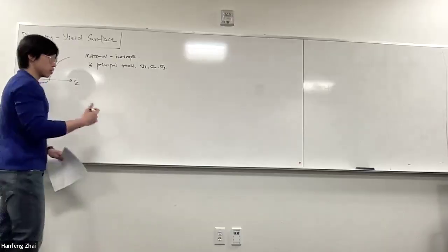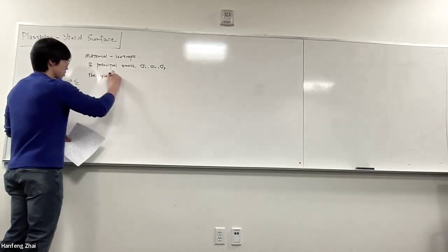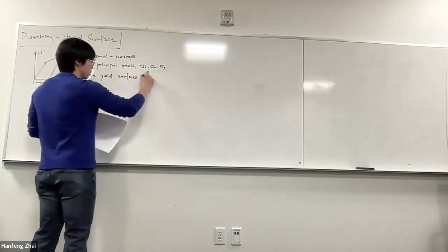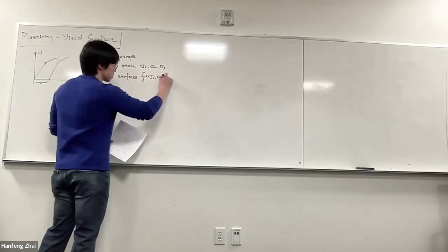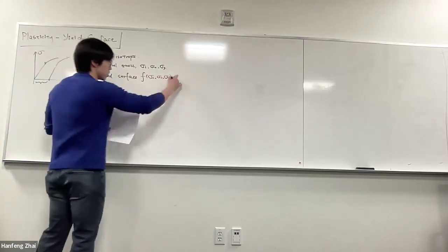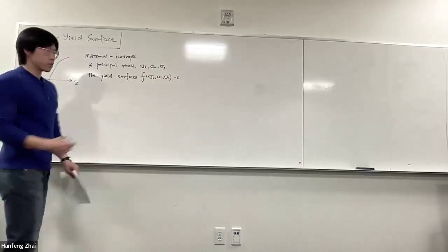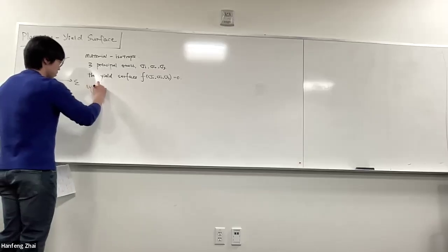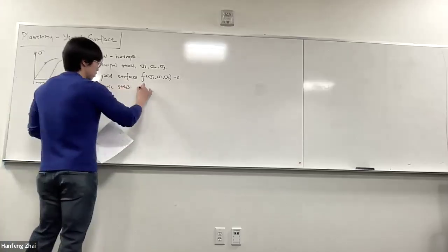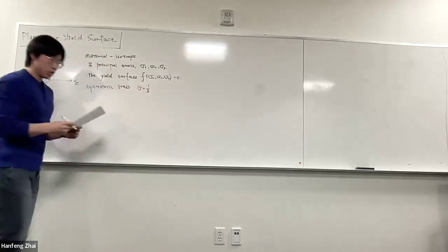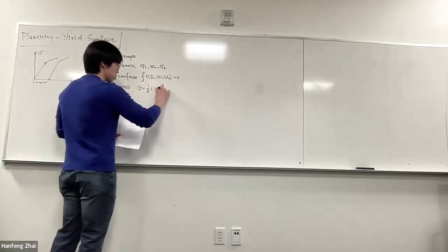So I can write the yield function, or the yield surface function, as a function of the three principal stresses, and the function equals 0. And recall another basic concept called hydrostatic stress, which is 1/3 of the summation of the three principal stresses.